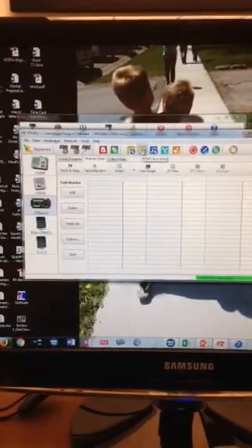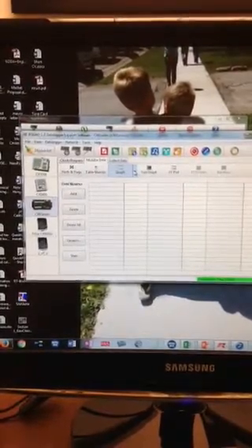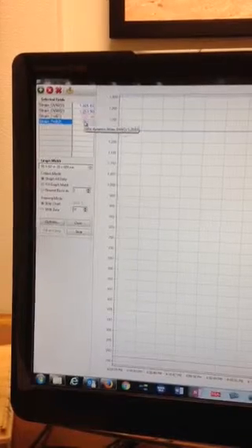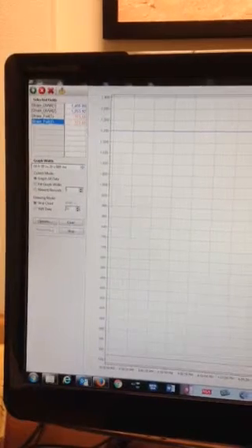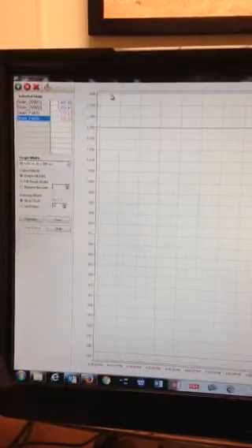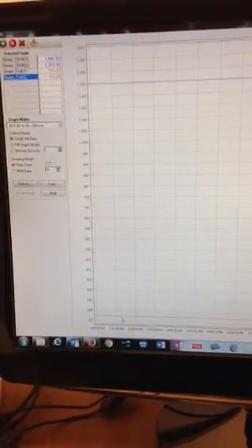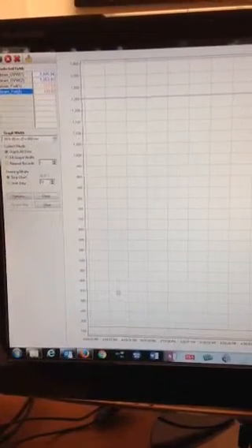So to do that, we're going to use the monitor data and graph, and we will use a real-time graph number 1, which is the one we've just been working with. Now, you'll notice that the vibrating wire strains and the foil strains are not in line with each other. So up here you can see the vibrating wire, and then down below here's our bonded foil and our bonded foil. What we would like to do is compare those two simultaneously.